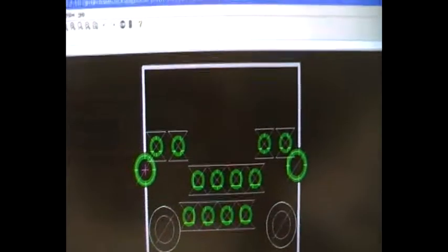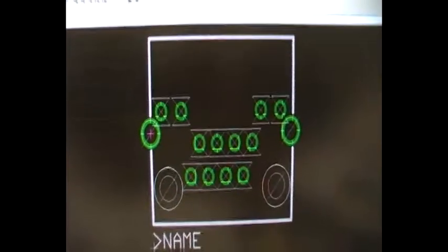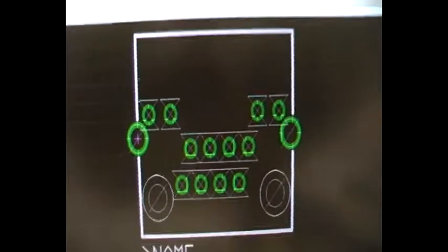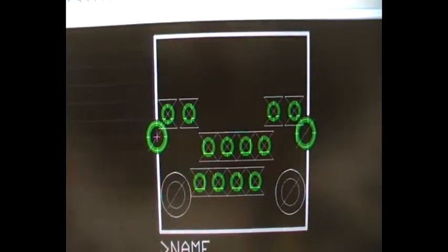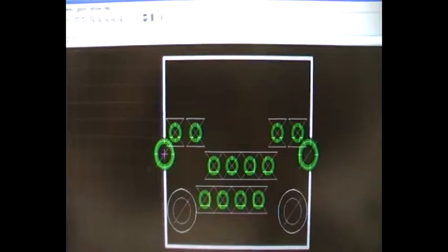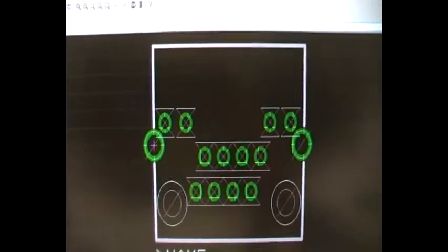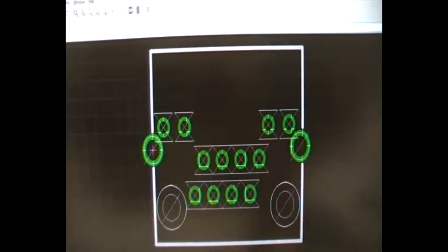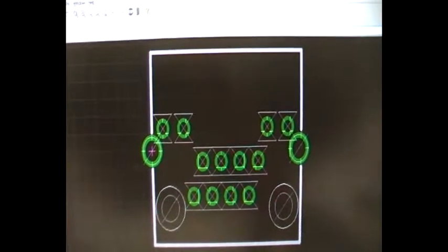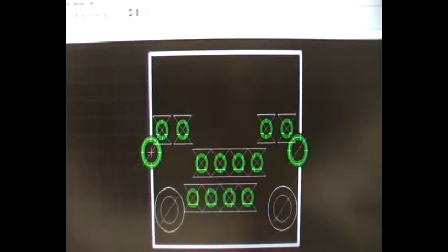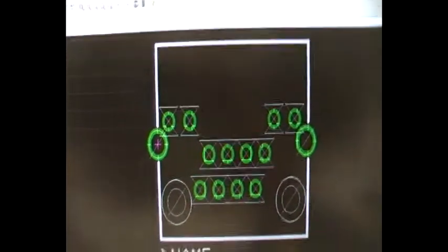So that connector is, like I said, an Amphenol RJ45 socket, and here's the final result. So I've still got my origin there on my reference pad, and I tend to leave it there. I know a lot of people prefer to have that origin in the center of the component, and maybe there is a way that I haven't discovered in Eagle, or maybe in later versions of Eagle you can have some sort of reference marker. Keep that in your library, and still have the origin in the center for picking it up and placing it and rotating it around that origin.